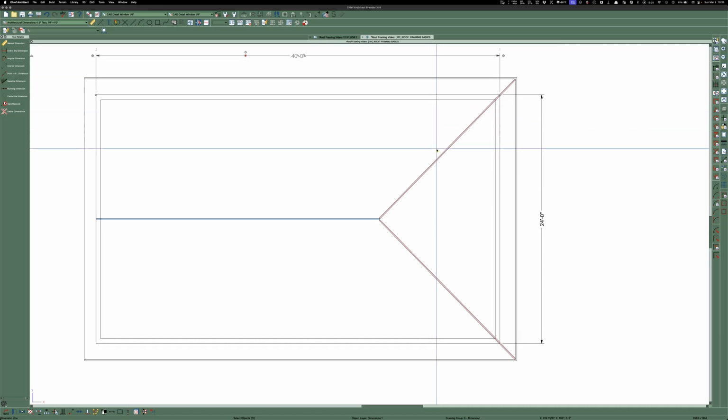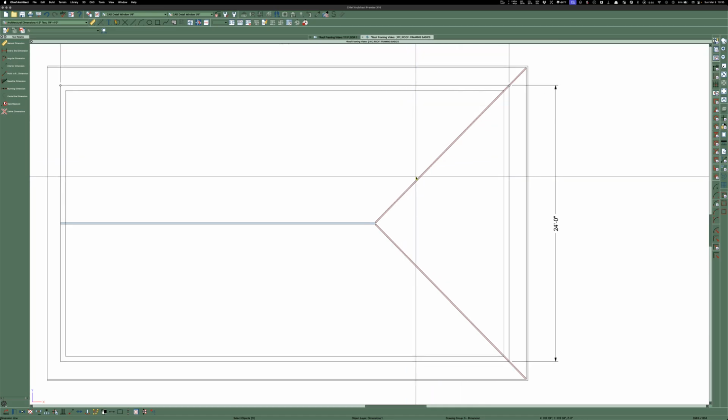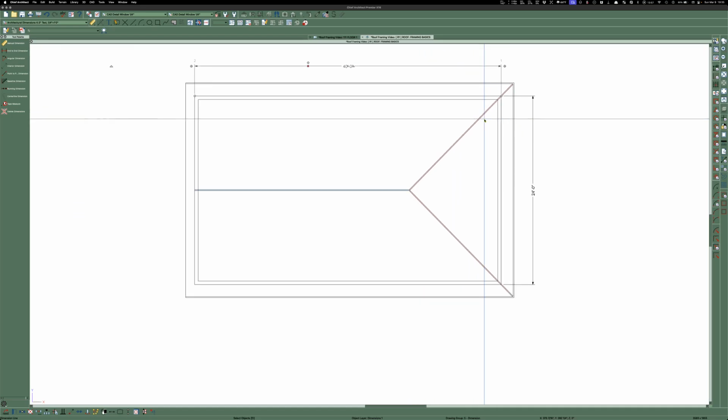And then come from the other side and do the same thing and do what you got to do to get this to where it's on the layout, and then tack it, and then go look. It should be straight. Because what you're doing is you're cutting to theoretical perfection, and you're forcing that perfection every chance you get. You're forcing it to be where it's supposed to be. And the only problem is sometimes you get lumber that's got variations in it, but the variations go both ways, so they kind of average each other out.